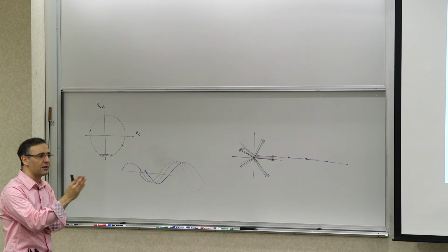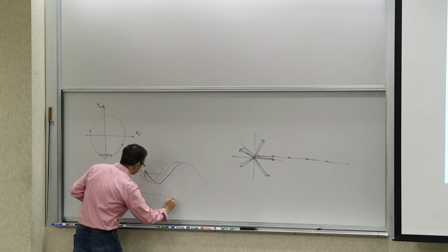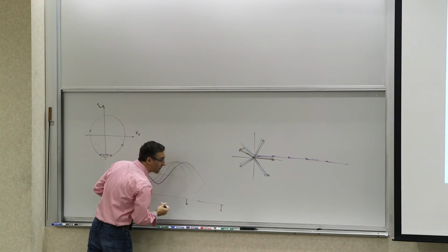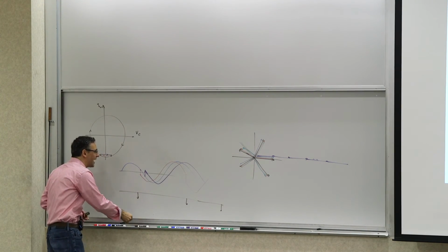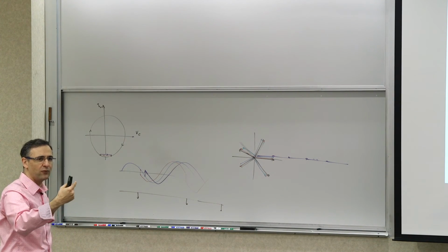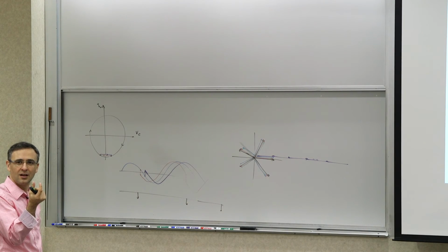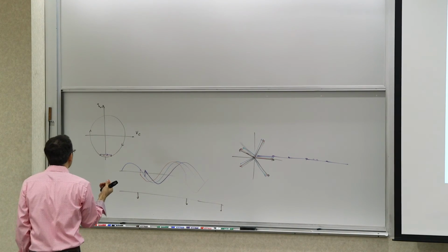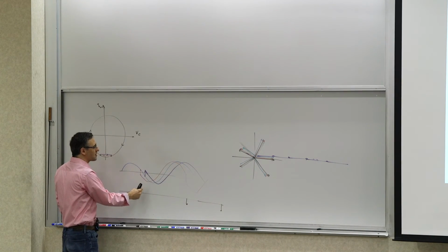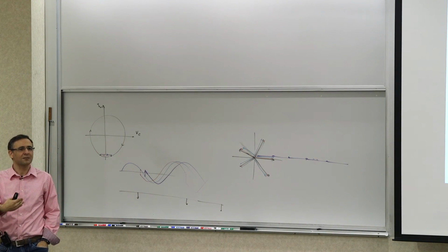So by having a periodic injection, an injection happening with a certain period, and if it has the right amplitude and happens at the right time, it can produce a waveform that's running at a higher frequency. The period is reduced. Although the natural frequency of the oscillation was that of the blue one, now the period of this oscillation is dictated by the period of the impulse train. So that's one way to think about injection locking.